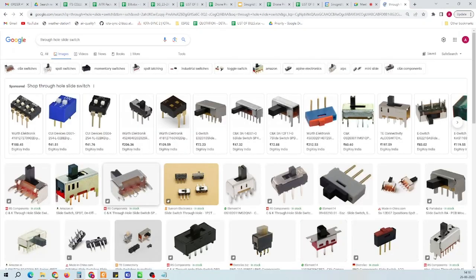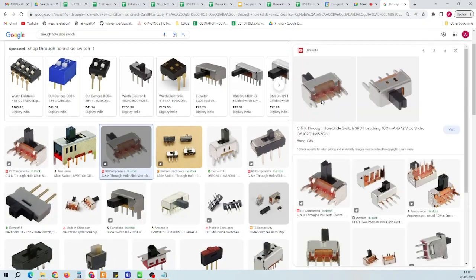So this is a slide switch that can be added, and if we move it from one point to the other, basically it has 3 pins which are electrically connected, and these two are just for the supporting part. There is a central pin which can either be connected to the left pin or to the right pin. So just by sliding it from one point to another, we can make the circuit, or we can break the connection of the circuit. I hope it is clear till this point.